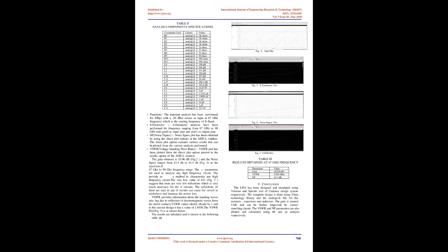Figure 1 shows the implemented high-frequency 3-stage low-noise amplifier. The inductor values are chosen such that they match the input impedance of the transistors for the next stage 1. The capacitors are used for eliminating the DC components, if any, and provide a good waveform at the output. The last stage consists of a common source stage that amplifies the power of the signal transmitted. Fig 1. Schematic diagram. 3. Circuit specifications.